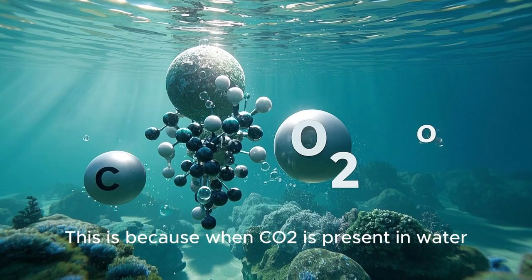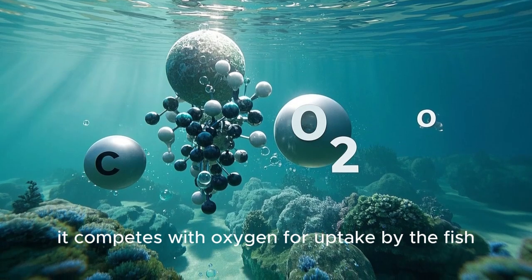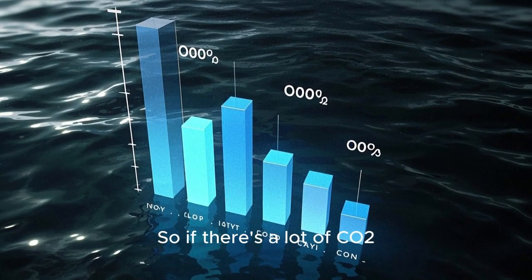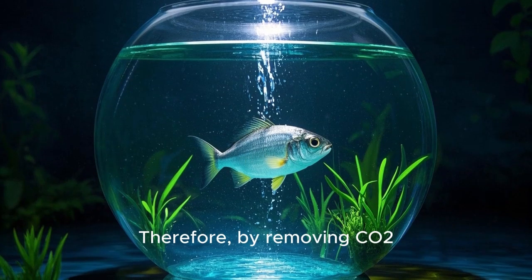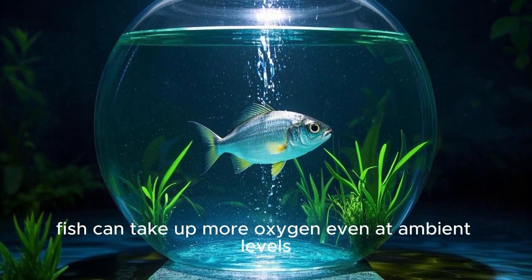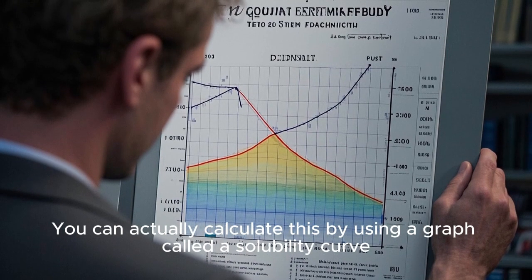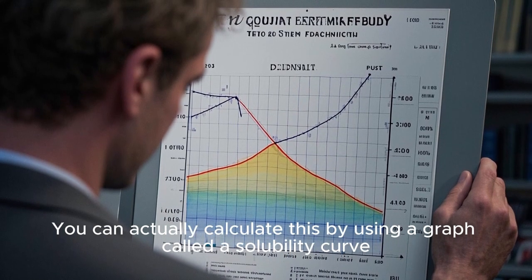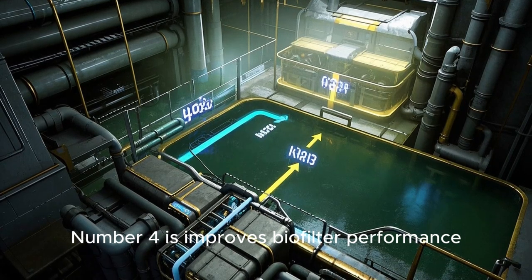This is because when CO2 is present in water, it competes with oxygen for uptake by the fish. So if there's a lot of CO2, then oxygen uptake is reduced. Therefore, by removing CO2, fish can take up more oxygen even at ambient levels. You can actually calculate this by using a graph called a solubility curve. Number 4 is improves biofilter performance.